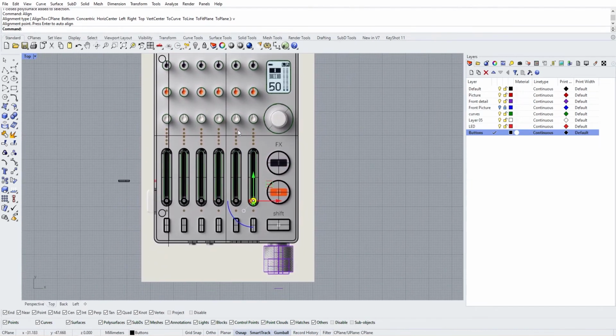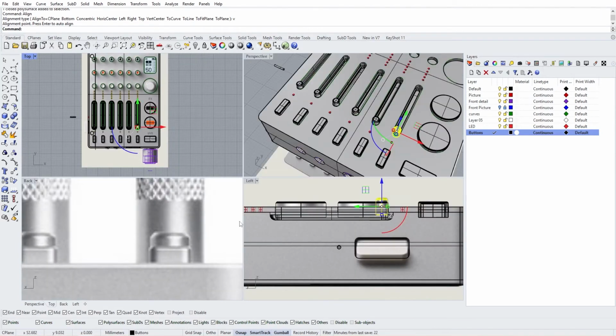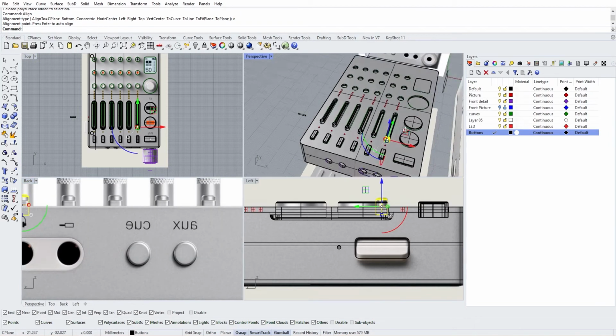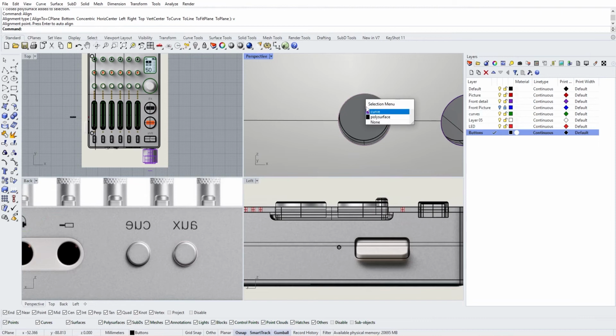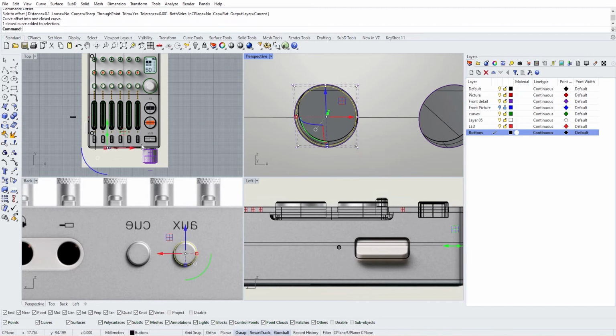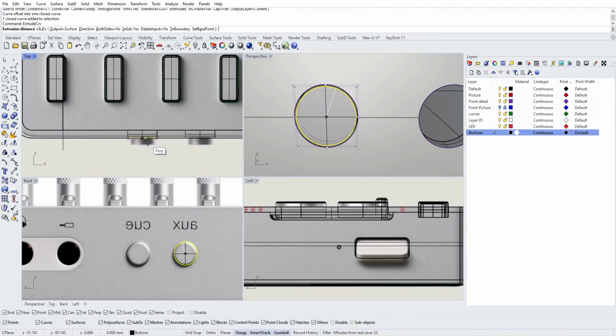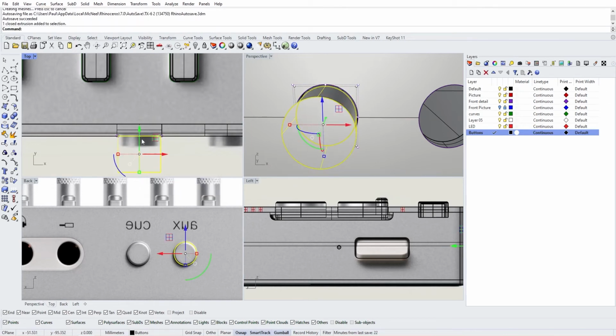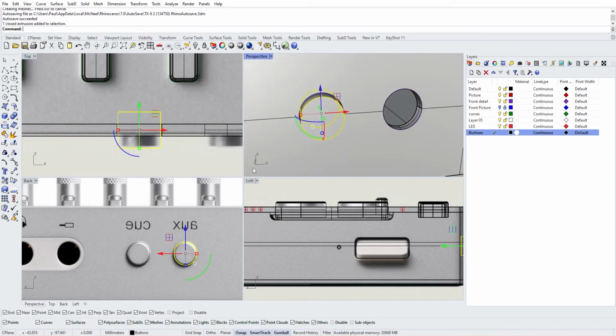So now we can do those buttons here. So from the front here, so let's go there. Let's offset them. So this needs to be extruded of 0.7. Let's say 1, so 1 plus 2 is 3. So let's extrude it of 3, move it of 2, and then we're going to put the same details.